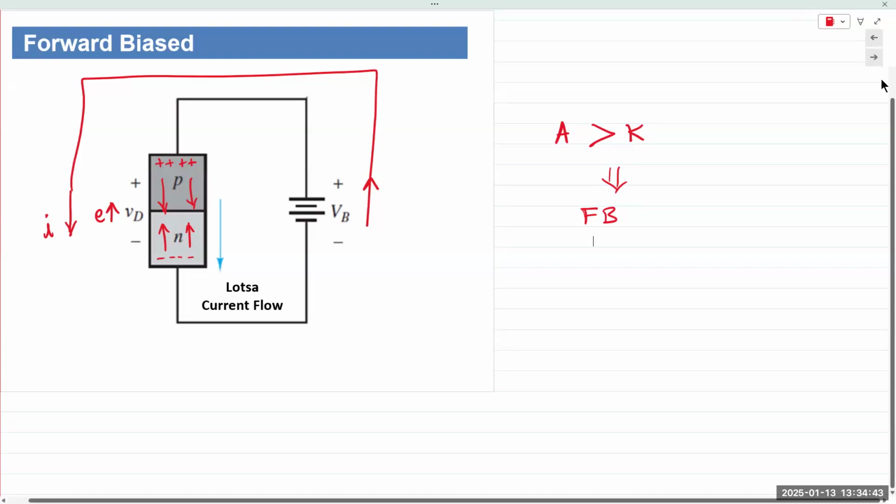But they are not as low as what we have in insulators. So when you create excess of charge carriers from external impurities, you have both kinds of charge carriers present in a material. So in a p-type semiconductor, you have intrinsic charge carriers that are holes and electrons. Plus, you have excess positive charges that are introduced because of the column 3 elements.